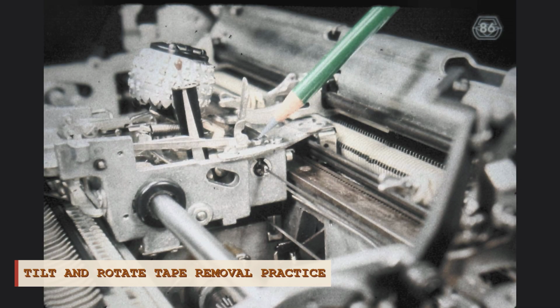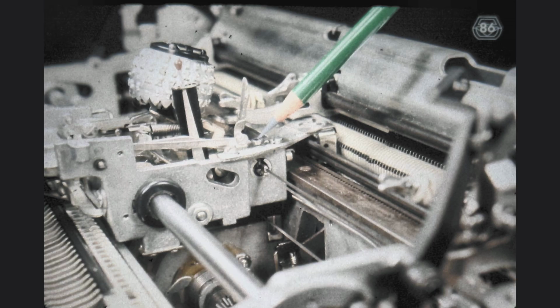There are various ways to take out the tilt and rotate tapes. We will show you one that starts with the right end of the tapes. As you examine the anchor spot on the right frame of the carrier for the tapes, you will find that the rotate tape is located at the bottom. Therefore, in order to take out the tilt tape, we must always first remove the rotate tape from this anchor spot. The job is actually very simple, because all we have to do when we want to work with the tapes is first remove, or somehow relieve, the spring tension so we can handle the tapes freely.